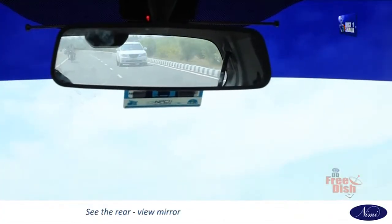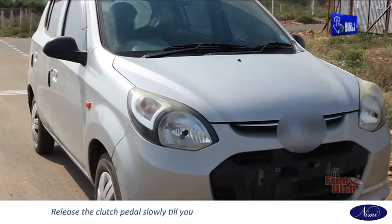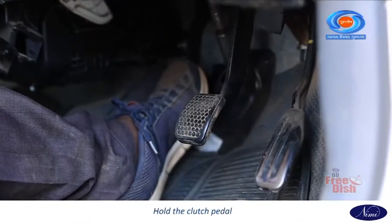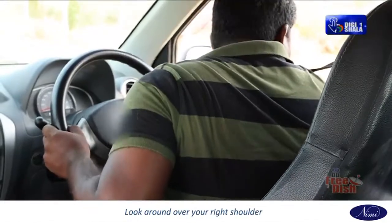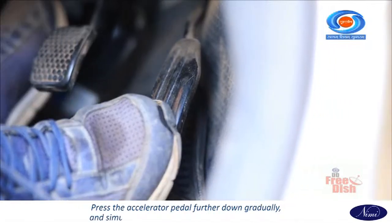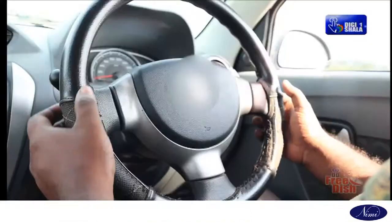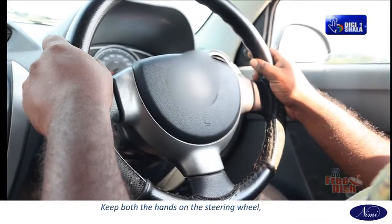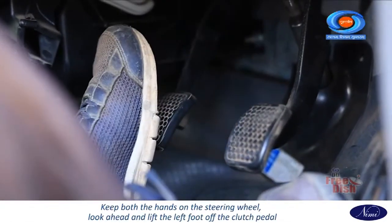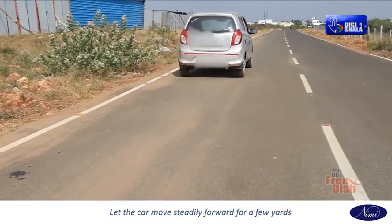See the rear view mirror for traffic coming from behind. Release the clutch pedal slowly till you feel the car is moving forward. Hold the clutch pedal. Look around over your right shoulder. Press the accelerator pedal further down gradually and simultaneously release the clutch pedal slowly. Allow the vehicle to move slowly. Keep both hands on the steering wheel. Look ahead and lift the left foot off the clutch pedal. Let the car move steadily forward for a few yards.